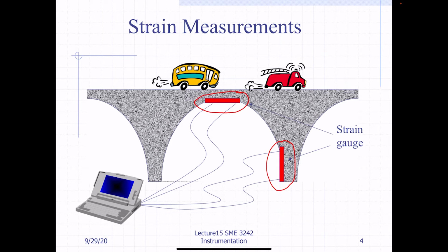beam. When a force is applied to a structure, the components of the structure change slightly in their dimensions and are said to be strained. Therefore, to measure these small changes, we use a strain gauge. Normally, an electrical resistance strain gauge is used due to its simplicity, inexpensiveness, and reliability.